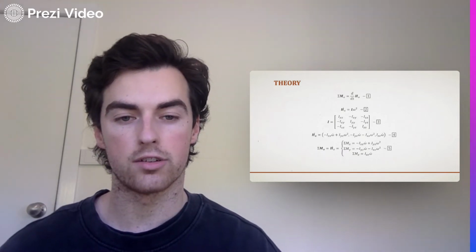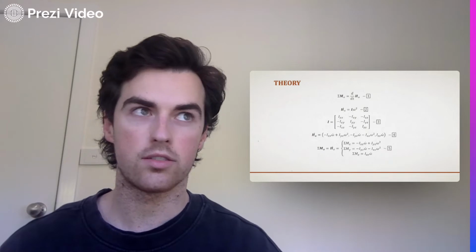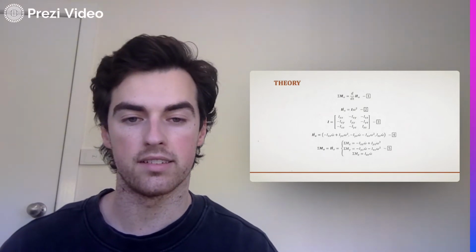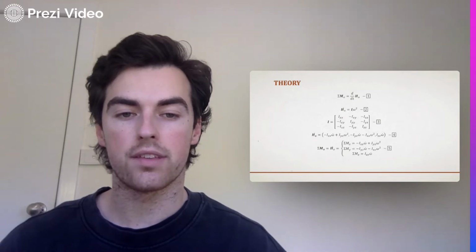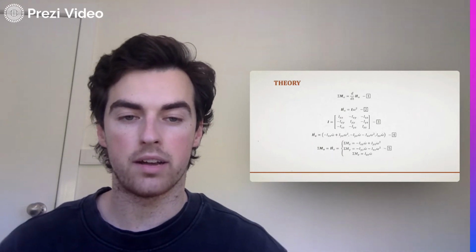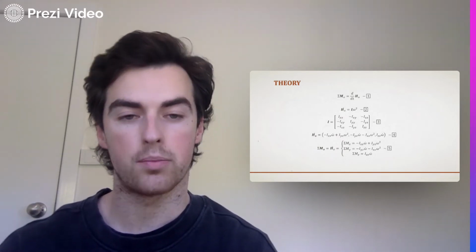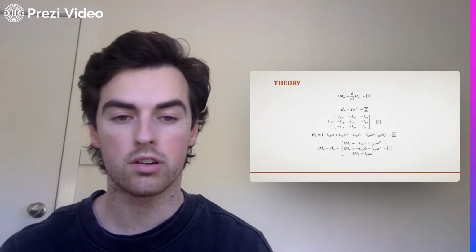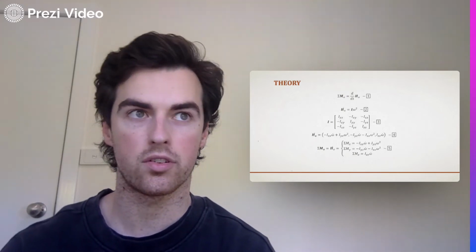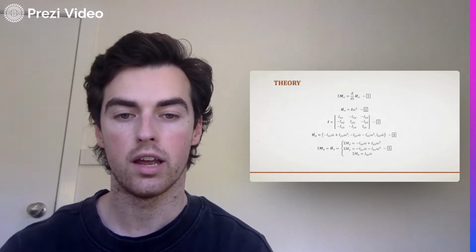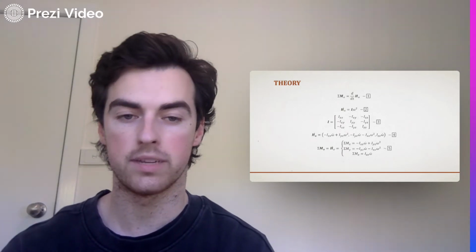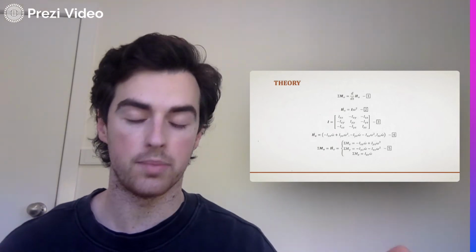calculated and then transmitted to each directional component x, y, and z, as shown by expression number 5. Now, if the system is dynamically balanced, the products of inertia will then equal 0, and if it's at a constant angular velocity, those accelerations will reduce to 0, and all those moments will be cancelled out, making a dynamically balanced system.